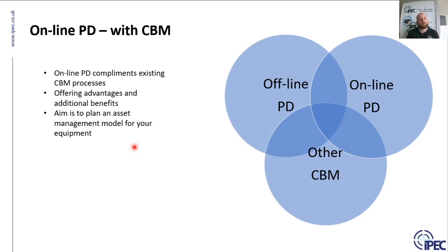And so what some customers do, for example, if I take Hong Kong, where they have many of our PD monitoring systems, they use our online PD to monitor 24 hours a day, 7 days a week, so they can always see a baseline condition of their equipment. If they find a particular problem, they can then do an online PD location, and then also take a shutdown and do an offline PD test. So if you like, that's a combination of existing standards which each back each other up.